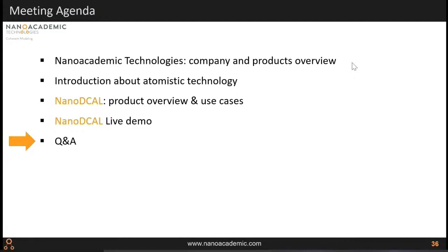Okay, another issue is regarding kinds of gate materials we can use. You have shown we can apply voltage, but we can use different kinds of split gate kind of arrangements. So it's possible, so that the gate material is basically specified by the dielectric constant. So you can use an effective solvent gate if you like. If you'd like a real atomistic gate, then you put the atoms, and it's going to cost more computational time, but you'll get the full interaction.